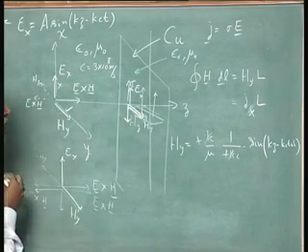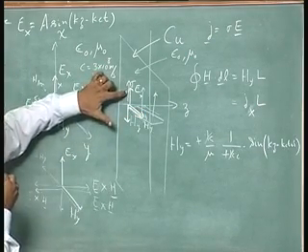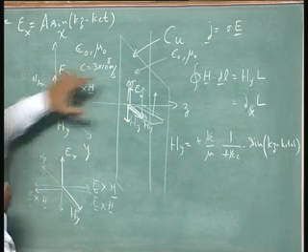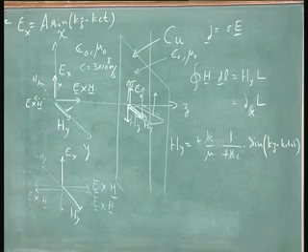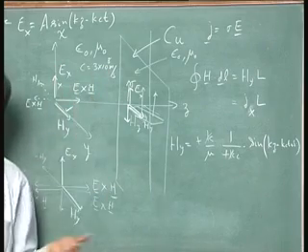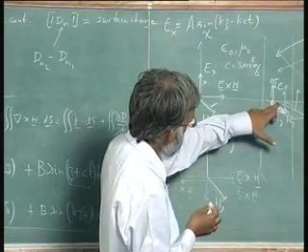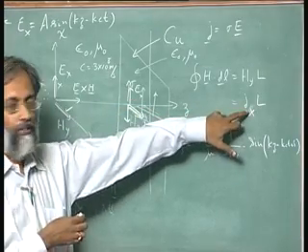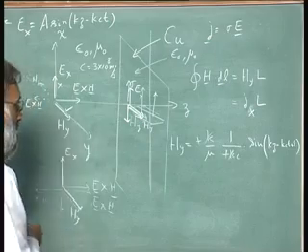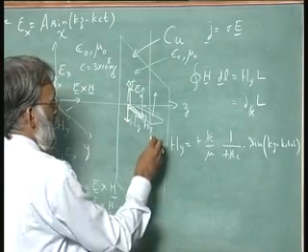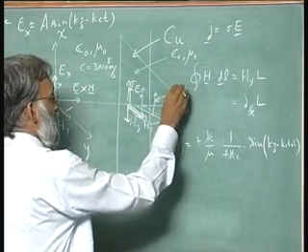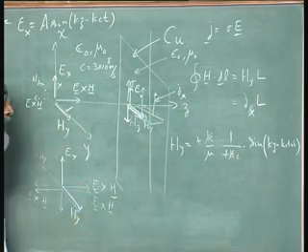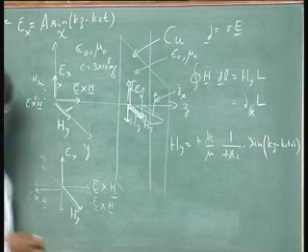Now what happens? At the wall, the plus Ex and the minus Ex cancel. I will end up with Ex 0, which is continuous. And because it is continuous, inside the metal there is no electric field. But the Hy's add up. I get twice the Hy, which supports a current. So inside the material, I am going to have Jx, but I am not going to have any electric field, and my J dot E will be 0.